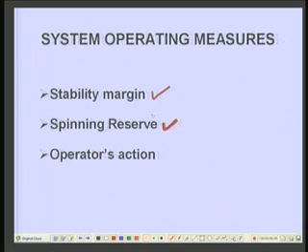because you have various reactive power sources like shunt capacitors, synchronous condensers, maybe SVC, maybe STATCOM and so on. Use them first and they load the generator, so that generator is operating at nearly unity power factor condition, it supplies the real power, so that it has a reactive power capability, and use this reactive power capability to save the system from voltage collapse. That is actually right at the design stage.